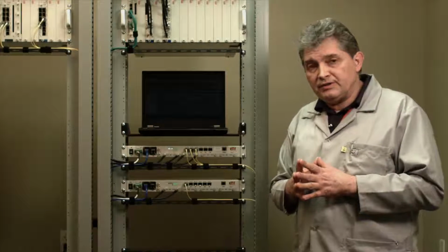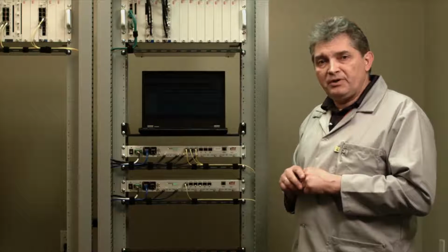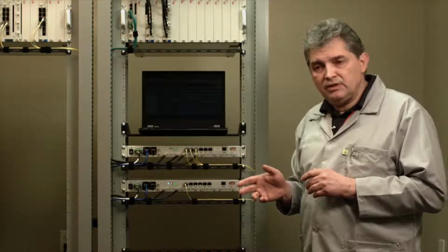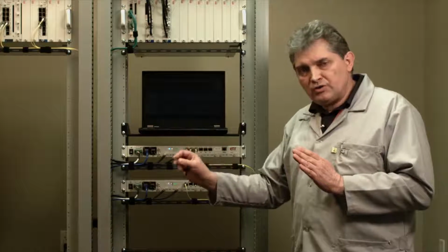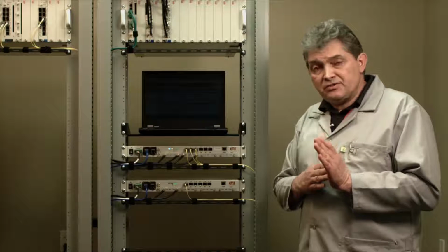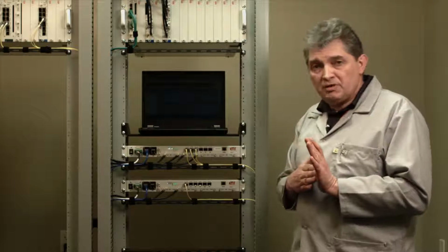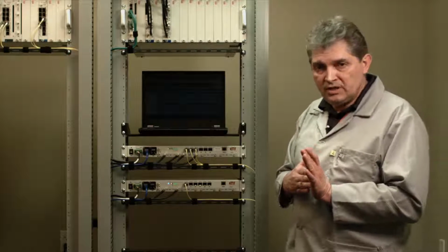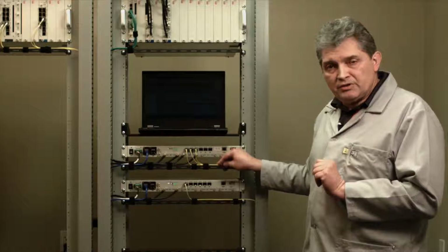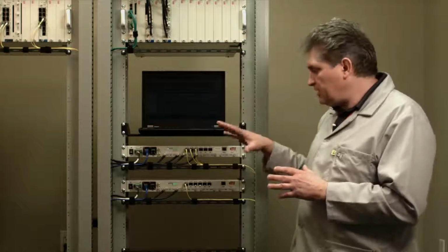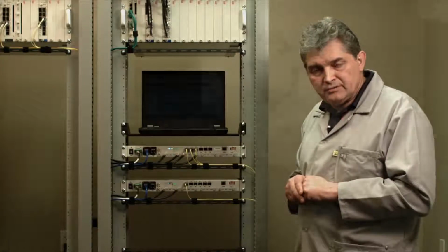The number of remote units that can be connected to a single host depends on 2 main parameters. One parameter is round-trip delay. It's actually the total delay from the base station through the system, user, and back to the base station. This round-trip delay is technology specific, and the most demanding technology or waveform is LTE. The second parameter is aggregated noise. Depending on how the base station is connected to the distribution system, a higher or lower noise level can be tolerated.